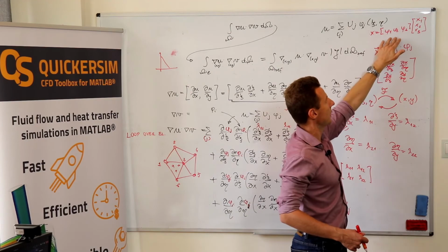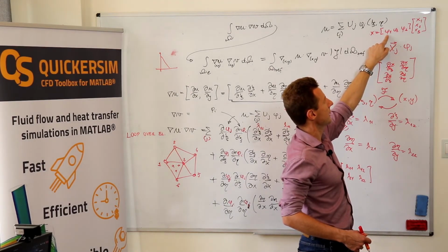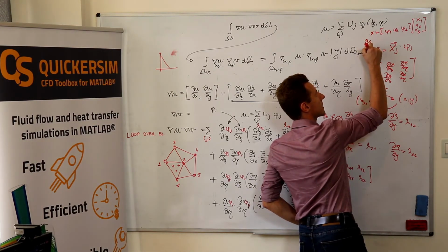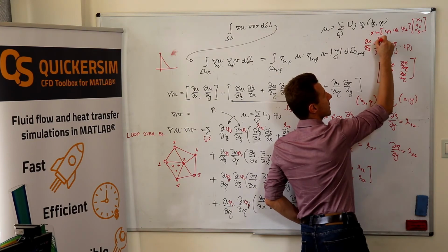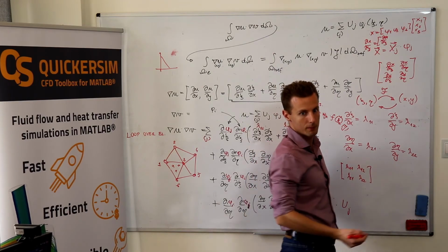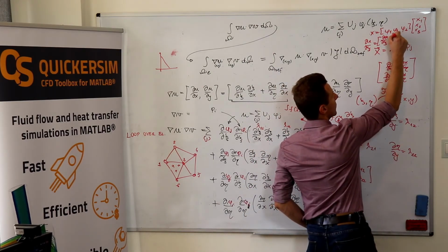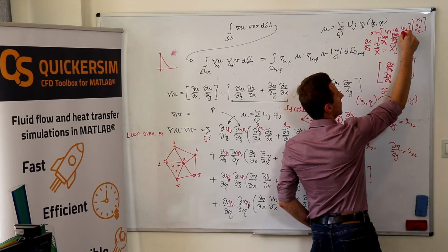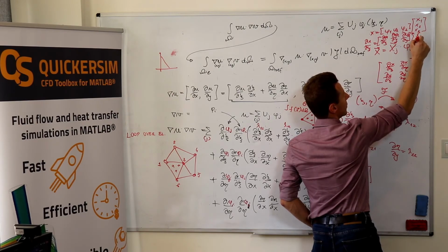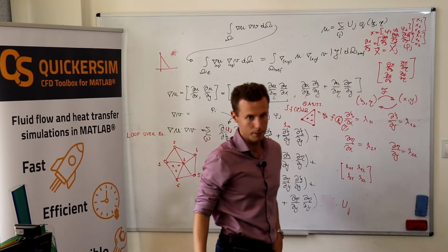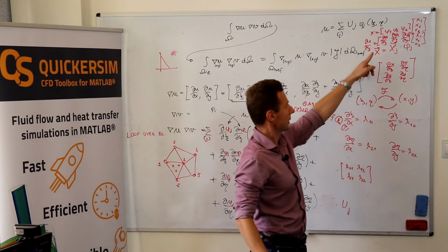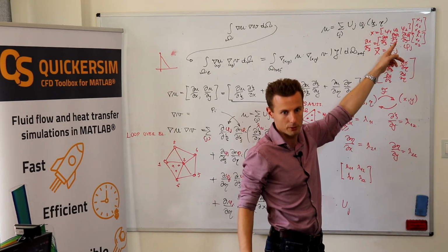But now, really, analytically, you can differentiate dx with respect to d psi. What does it mean? It means d phi 1 with respect to d psi, d phi 2 with respect to d psi, d phi 3 with respect to psi, times the same vector. And because you know the explicit formula for shape functions, you can calculate it on a sheet of paper.